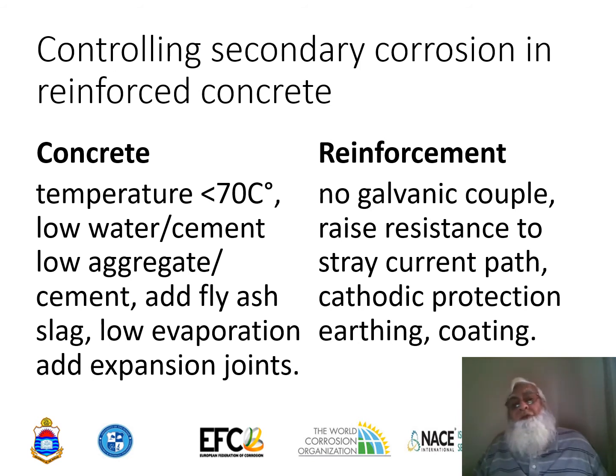Then it's always good to earth the building, or earth the reinforcement, so that any stray current which can pass through the soil and enter the structure, instead of damaging it through corrosion, can go through the earth and the earthing system instead of coming into the reinforcement.